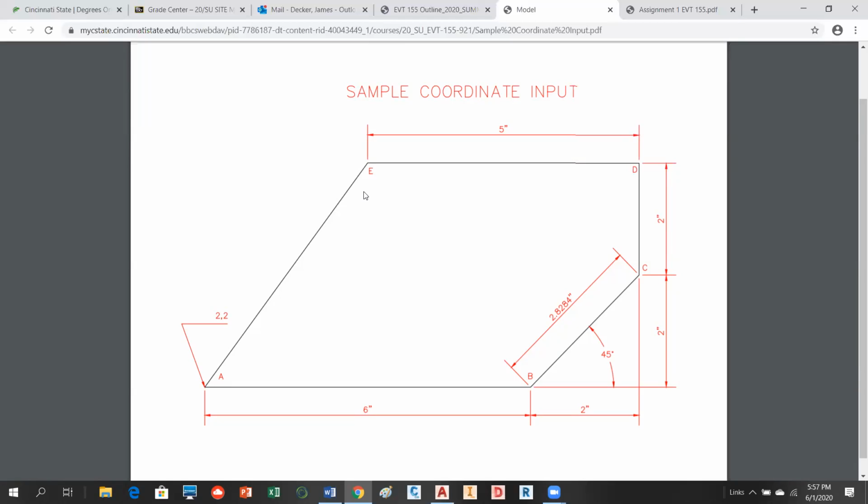And the good news is we're not going to have to deal with it a lot, but we're going to deal with it a little bit, because if you don't ever learn this technique or this process, it really limits what you can do in AutoCAD, okay? The other type of coordinate is called a polar coordinate. And the polar coordinate's a little bit harder to use, but what it's doing is it's going to reference a distance, okay, along the line, and an angle off of the x-axis.